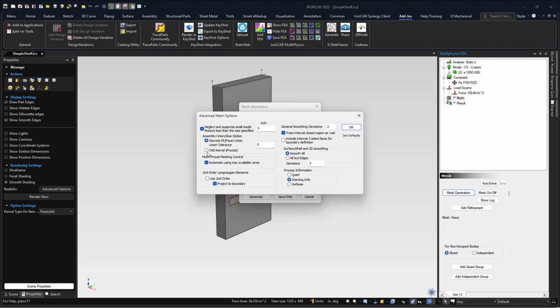But you can also use the CAD precise model here if everything's precisely aligned, no interferences, no gaps inside of there. This can be unioned using basically IronCAD's kernels, the ACIS or Parasolid kernel, to give you the results in a precise fashion, and usually is pretty much faster than the facet-based process, because this does have to account for the tolerances and things like that it's working with. So that's just some information that you can use.